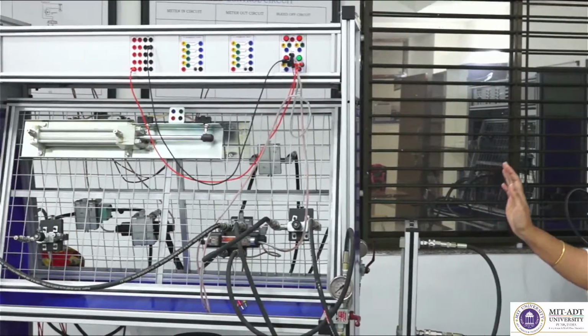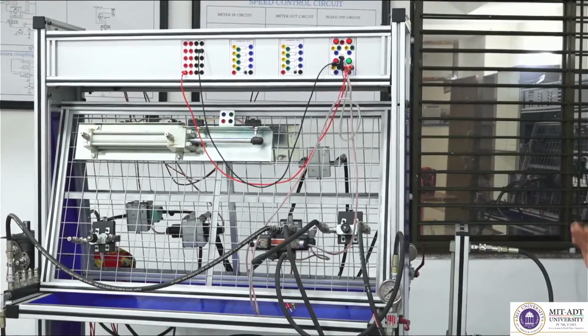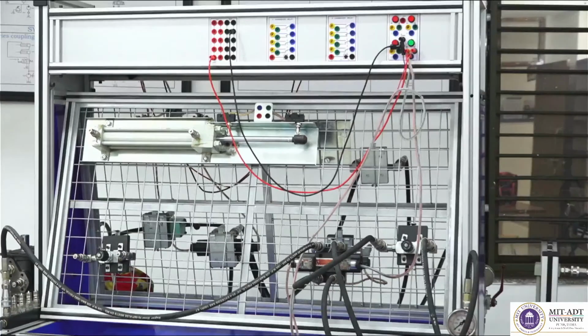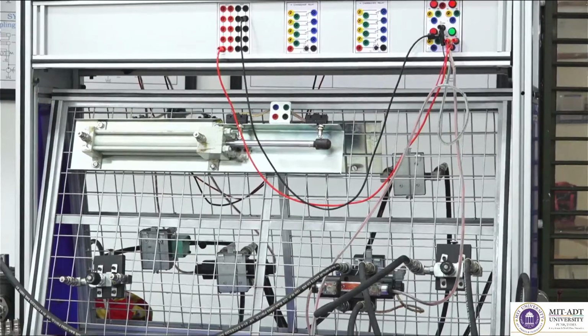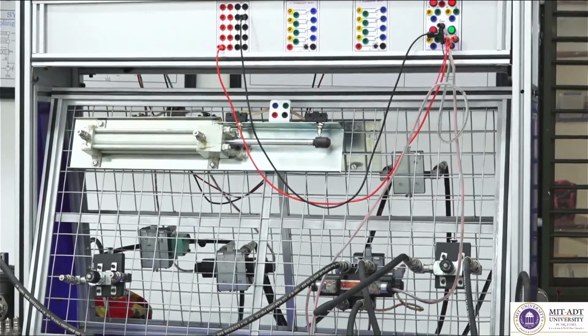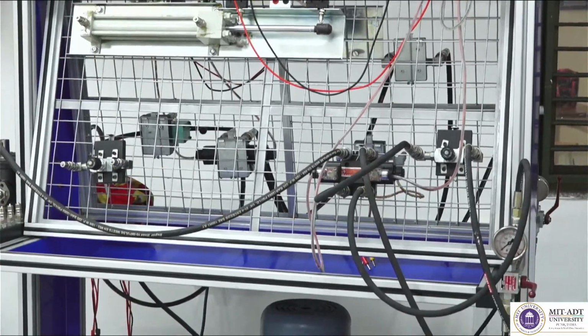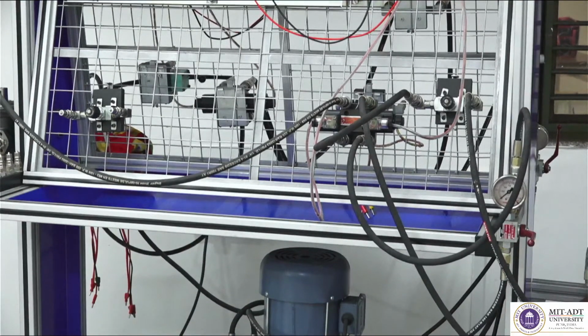Okay, fine. This is a customized one. The pressure rating for this kit is approximately 60, we can reach up to 60 bar. Velocity we can control with the help of the FCV, and we can monitor that velocity. We can achieve a velocity of 3 meters per second, 5 meters per second, which we have already achieved. And we have used a balanced vane pump inside the whole kit.